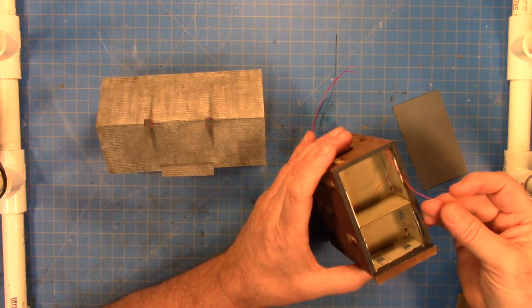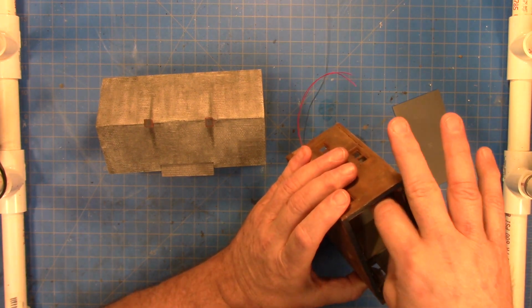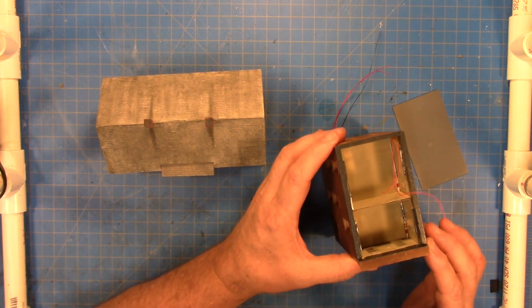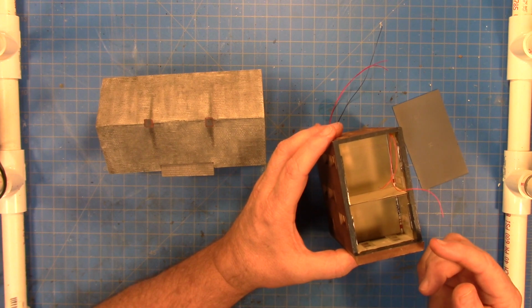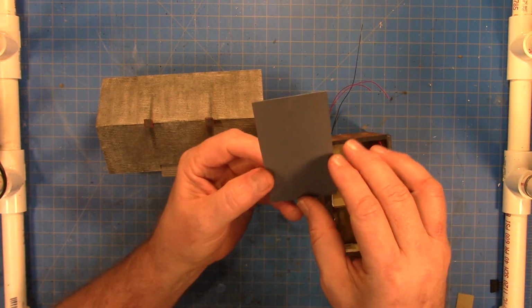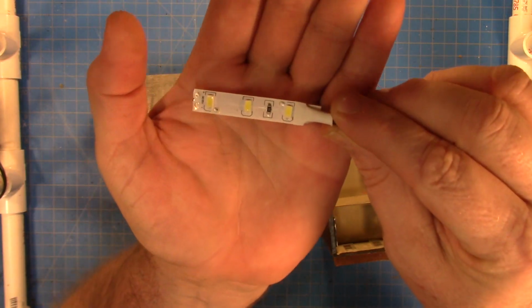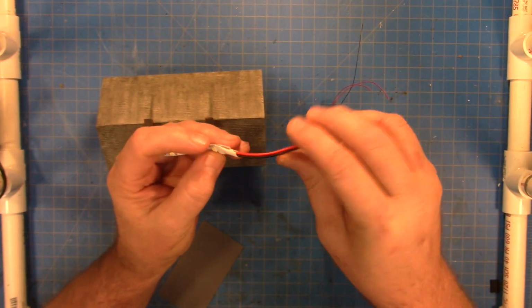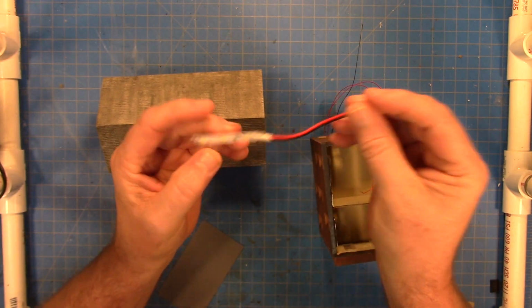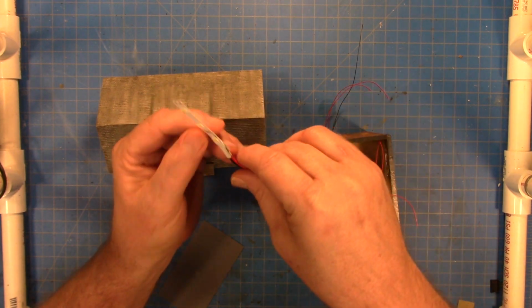You can see I've got 2 wires coming up here. These are the positive connections to the LEDs. What I'm going to do for the negative connection, since they're all common, the LED strip that I bought comes with double-sided tape, so I will stick 2 of the LEDs. I'm just cutting them. They're very similar to these. However, these are 12-volt LEDs, and they won't turn on using the 5-volt output of the Arduino Nano. So I ordered some 5-volt version of this, and you can just cut these.